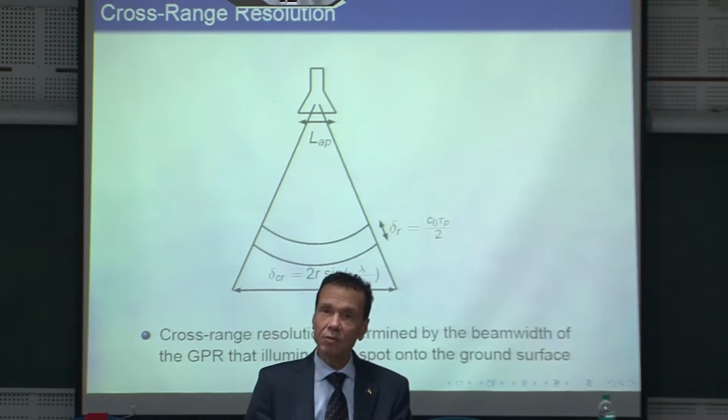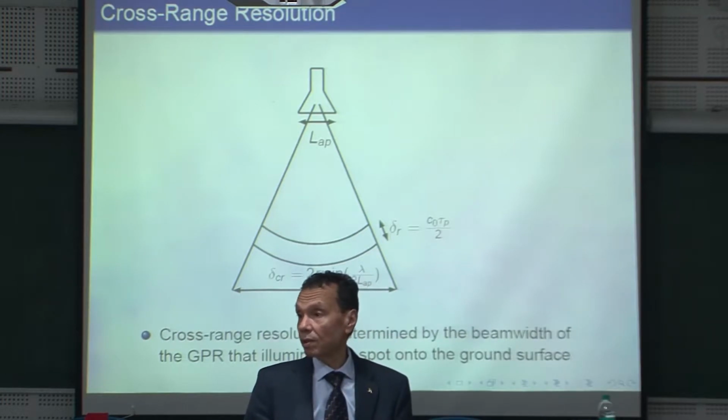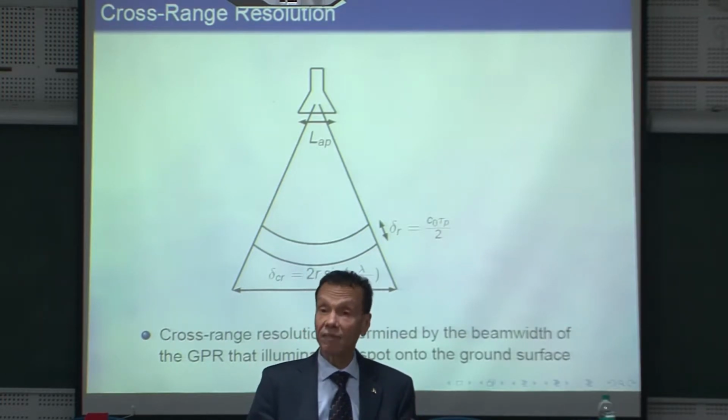So for array applications, you really don't need a high directivity unit pattern, because a high directivity unit pattern deteriorates your array factor.